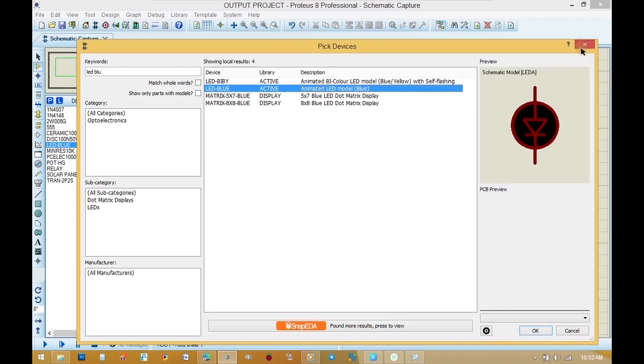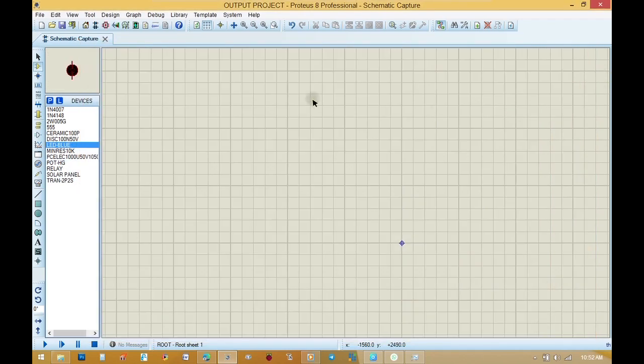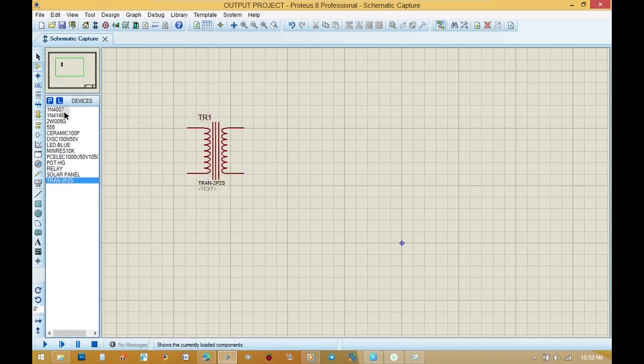But in this our project, we are going to construct it to operate in astable multivibrator. That means it will be going and coming, that is high and low, high and low, high and low at intervals. By this method, we will be able to increase the brightness of our LED and reduce it using a potentiometer. Like you are seeing it here, we are selecting it now. Using a potentiometer, do this selection, increase the brightness, reduce it, everything. This is a very good project.